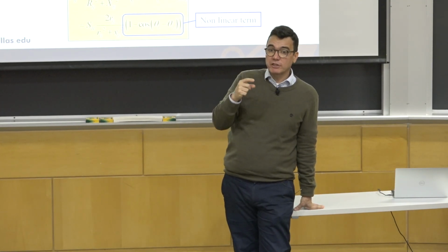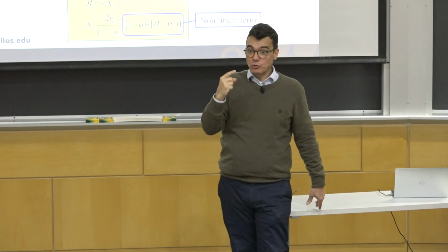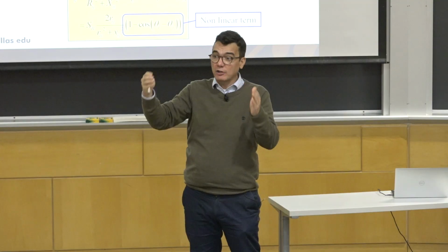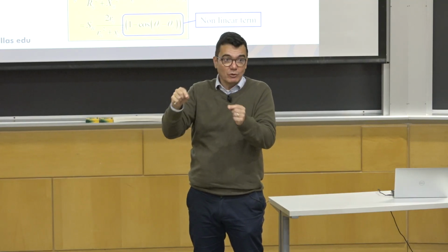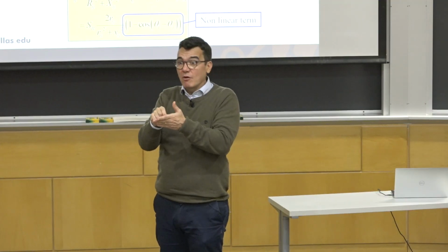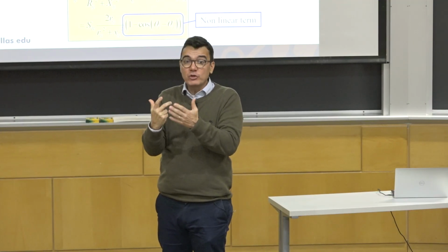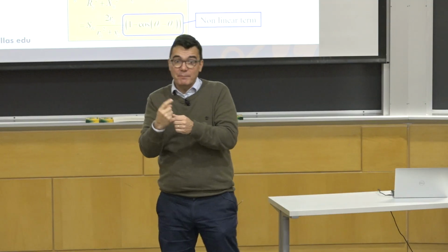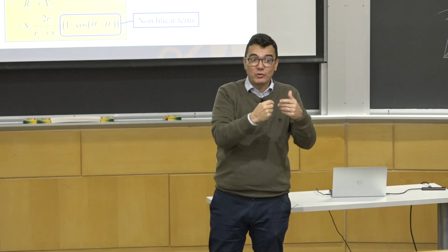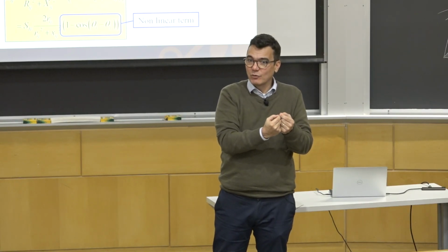So if the voltage is 1, and in this segment of the circuit the nominal voltage is 400 kilovolts, it means that the real voltage in this node is 400 kilovolts, because the per unit value is 1. But if the per unit value is 1 in a place where the voltage is 20 kilovolts, it means that the real voltage is 20 kilovolts. You see what I mean?